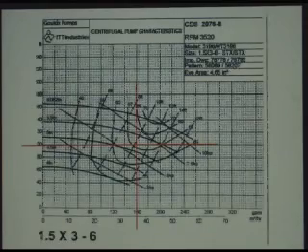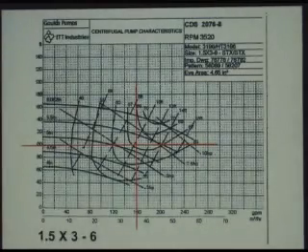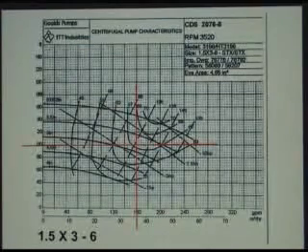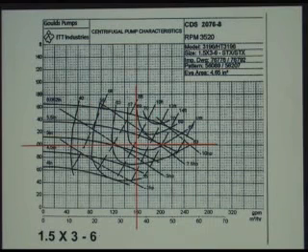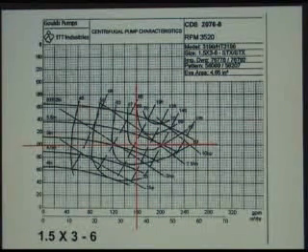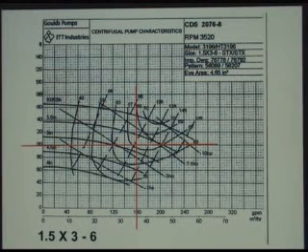So this came from Gould's Pumps. We buy a lot of things from them. And I picked a point at 160 GPM flow at 100 foot of head, operating at 3,600 RPM. This is model 3196. It's a 1.5 by 3-6, that identifies as 1.5 inlet, 3-inch outlet, and a size 6 impeller, 4.65 square inch impeller eye, and a certain pattern for the impeller.